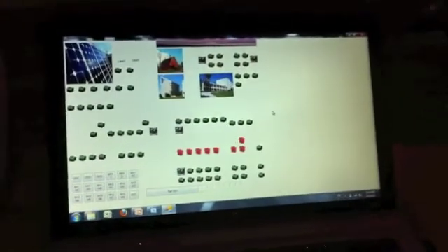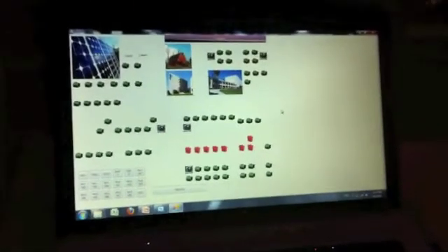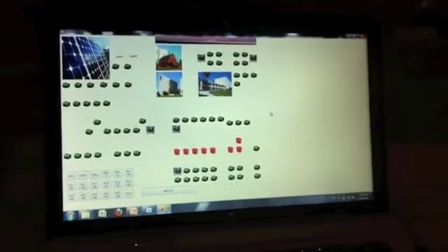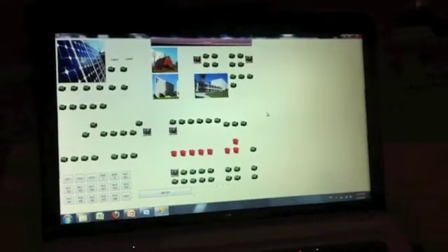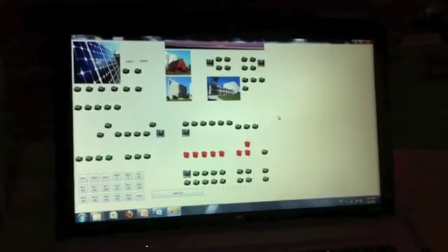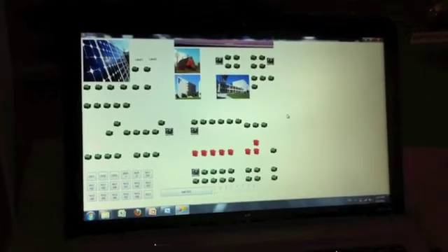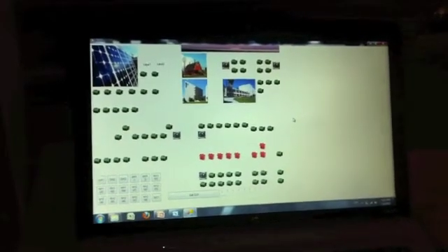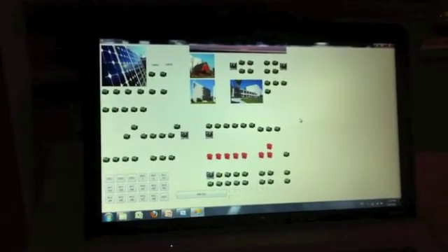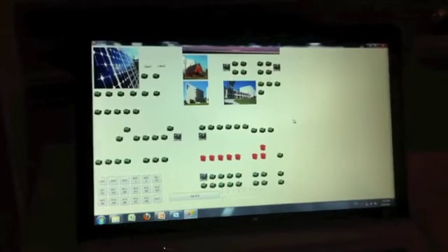Now, the way it works is that the board actually sends in a binary value, which it gets through the main PIC, which sends through a serial port, into a USB port, into the computer, digits representing groups of houses on the board, with a 1 being the house is on and a 0 being the house is off. When it makes it to the GUI, it actually comes in as 4 bytes of hex, which is base 16, which is then read by the computer as a decimal value.